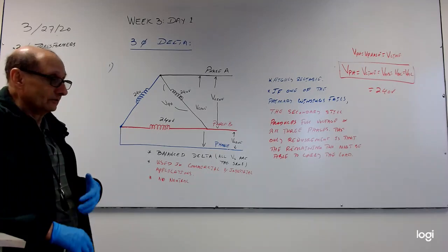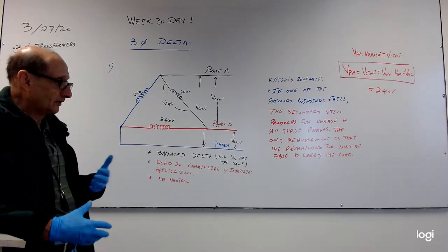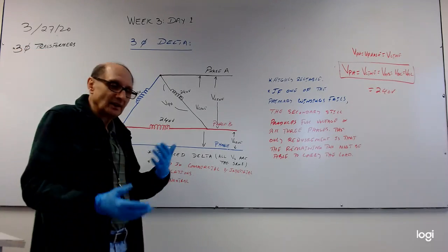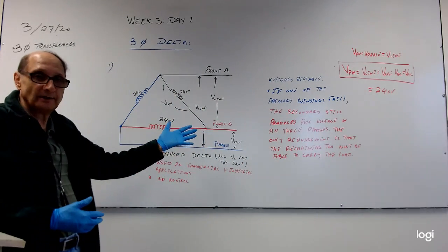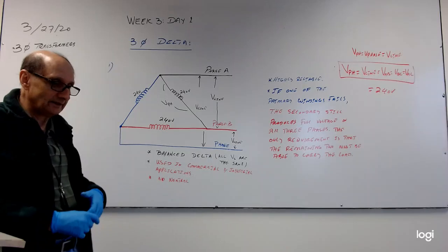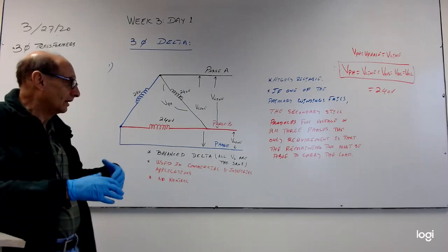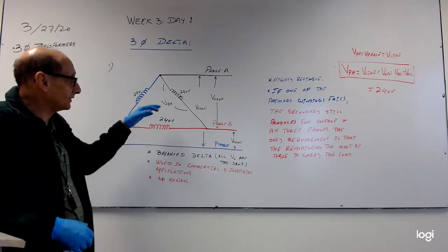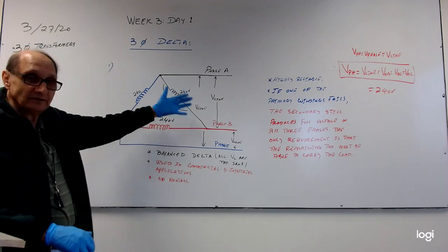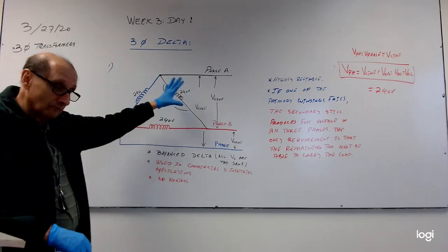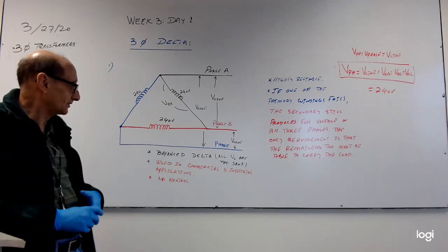Okay. As an electrician, you have to know what it is and how to make the connections. If you have to connect a motor using delta configuration or three-phase circuits, this is where you are going to see them. Any device that doesn't need neutral, this is good for those applications. Or devices that need constant voltage, like motors that require 240 volts, then definitely this is good. Balanced load, voltages are the same. We cannot have different voltages. If you get different voltages, then we get an unbalanced system.